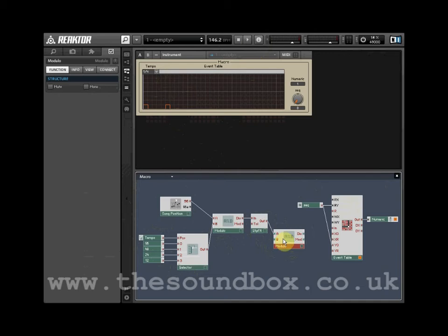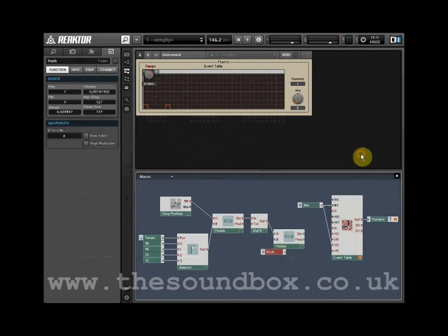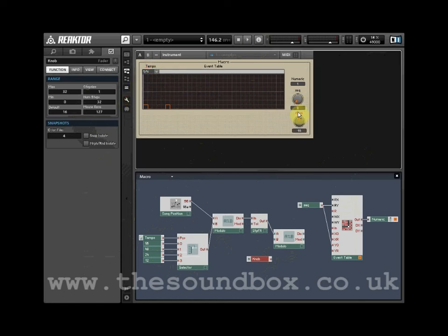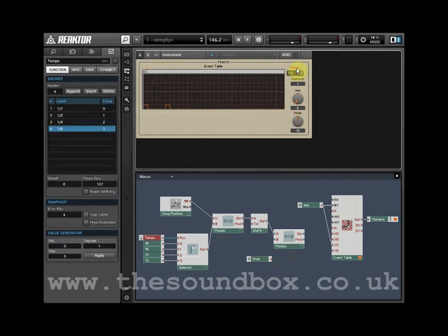Right-click, select Built-in Module, select Panel, and select Knob. The knob is going to control the amount of steps that we have in the display. It will allow us to lengthen or shorten our loop. Using the range fields, let's make maximum value 32, with 32 steps. Unlock the panel view and arrange the knobs. Label the knob Steps.